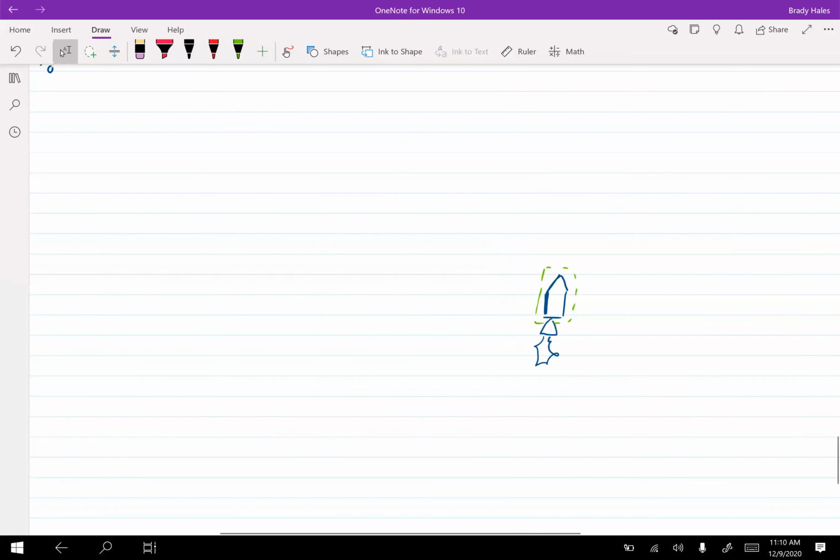So we will have some alpha G_sun coming in, and then so no conduction, no convection. What are our three types of radiation, right? We have irradiation, we have emissive power, and we have radiosity. I'm going to choose not to use radiosity here, although you could. I'm going to just say we then also have some emissive power coming out, and we want to know the steady state temperature of the rocket wall when it's a distance Mars away from the sun.